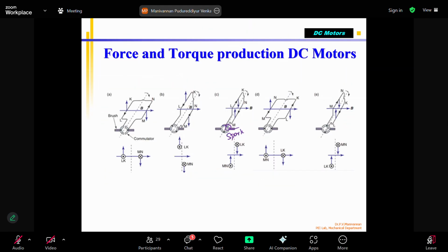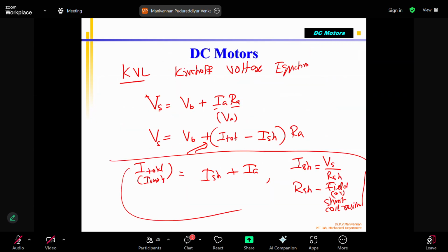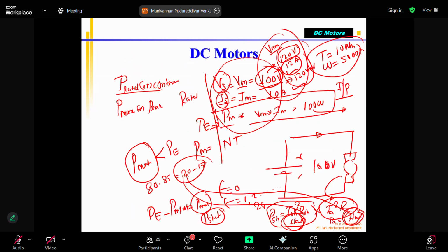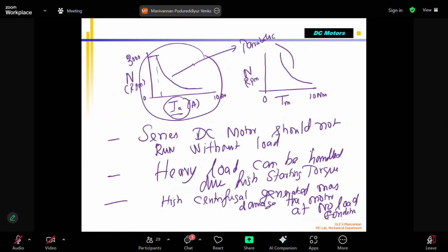During that time, both brushes are disconnected and the current flow is stopped. Then a spark is created. So that produces EMI, electromagnetic interference. Just like your spark plug, the DC motor commutator brush assembly also creates EMI noise. Due to electrical sparks, electromagnetic noise is created. That is one of the drawbacks of DC motors.